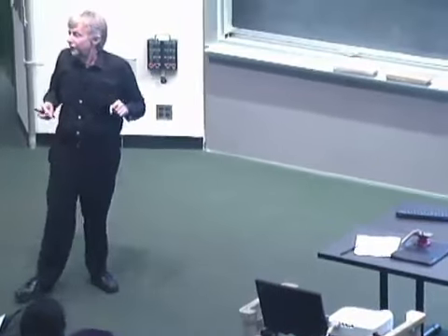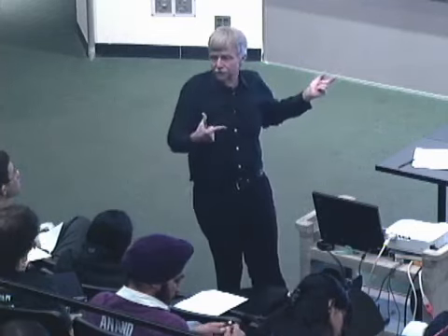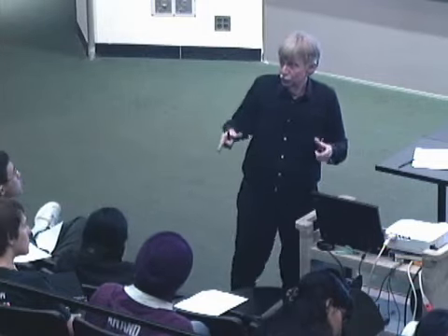By contrast, we might do something cleverer. We might linearly extrapolate between samples. That is commonly done in picture processing. The reason we use the two different schemes is that psychophysically, the things that are important to your eyes and the things that are important to your ears are different. So you would hear the errors more if you did the linear interpolation, and you would see the errors more if you did the other interpolation. And we'll do lots of examples later on in the course, so you see why that's true.